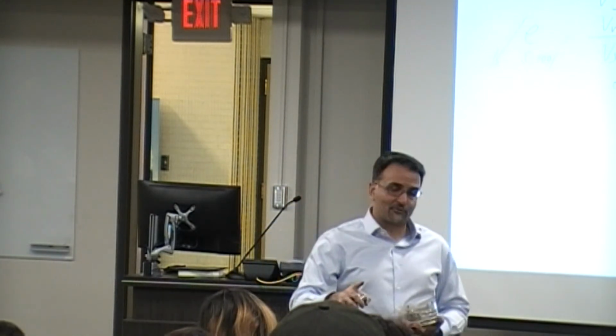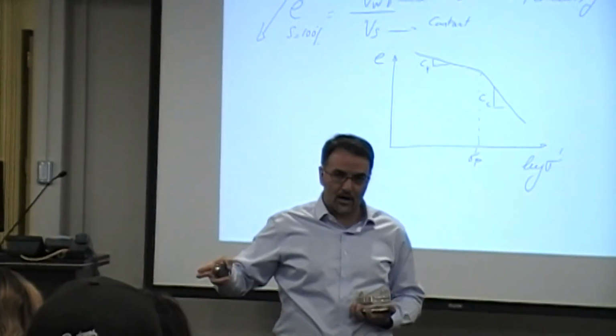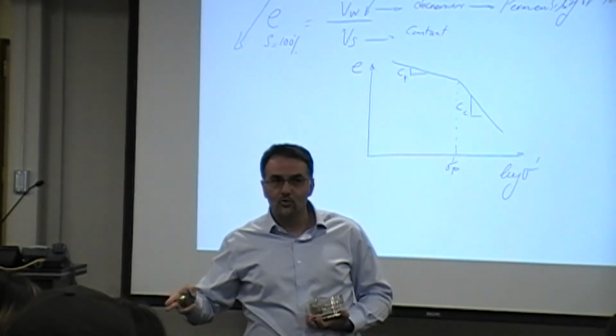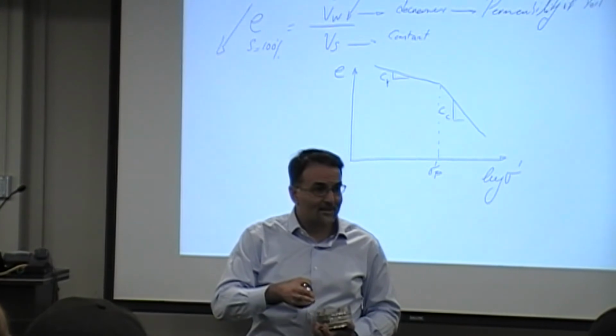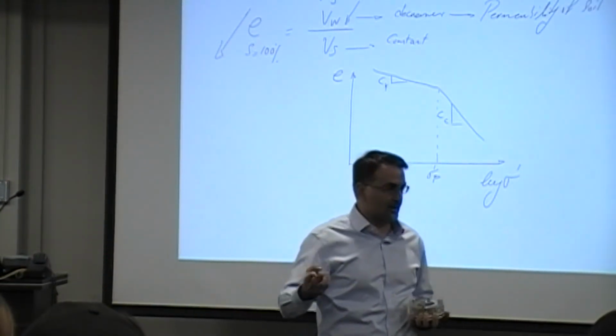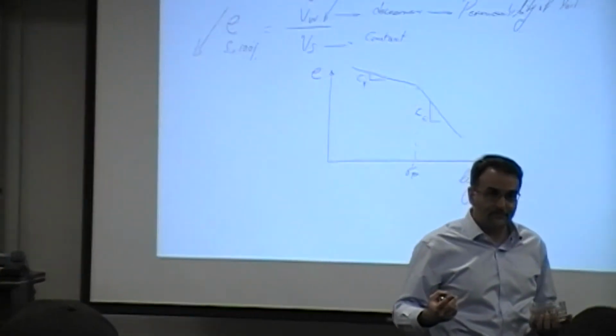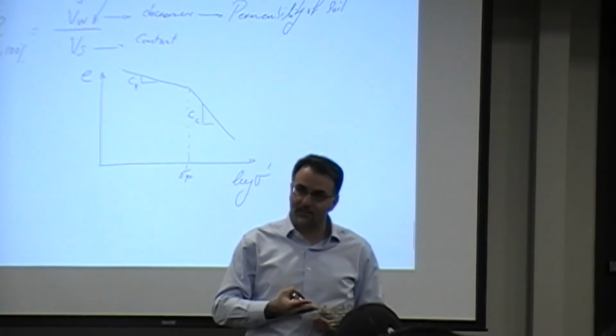Also, once we finish the 7, after the 7th day, right, there are 7 stages, right? Every time we do it for 24 hours. And then we start removing the loads incrementally. Now, what happens here? Right, remember in the previous lecture we talked about the concept of swelling, right? We had consolidation, primary consolidation, and swelling behavior.